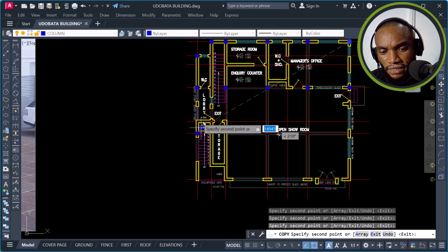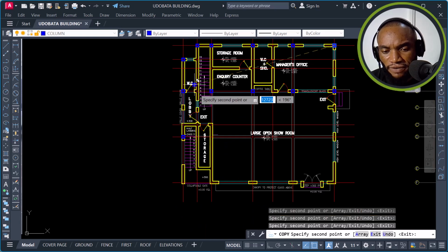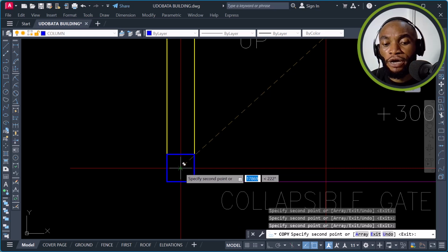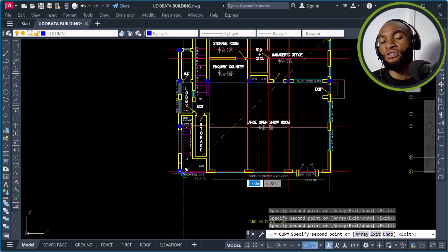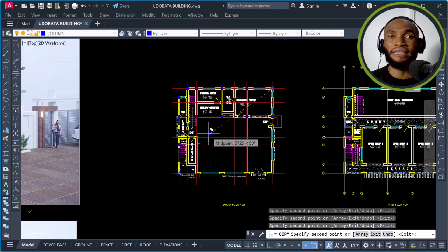From here to here is not that long. That's fine. I'll come again and place this here. Now, how I place my own column points, when you are going to practice on your own design, whether you use this building plan or another one, you can choose to place your own column points differently. The whole end point is that the building should be stable, and the cost of construction should not be too expensive.